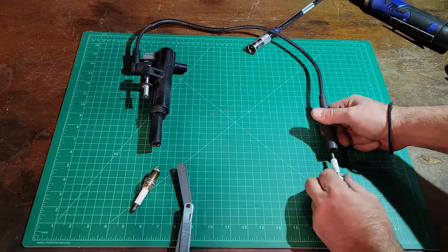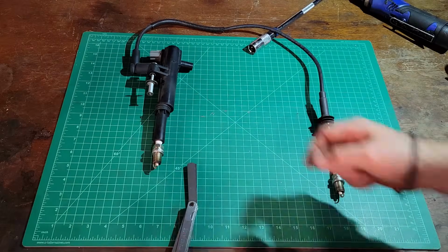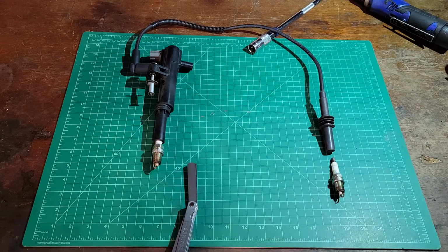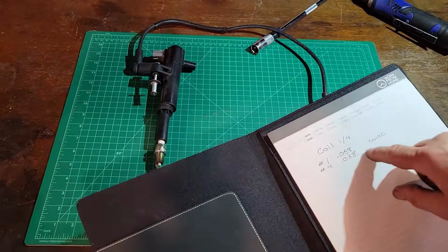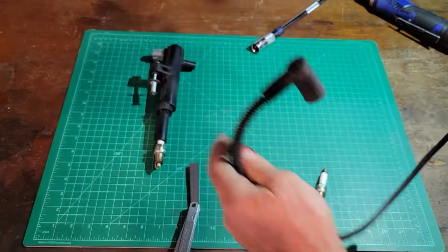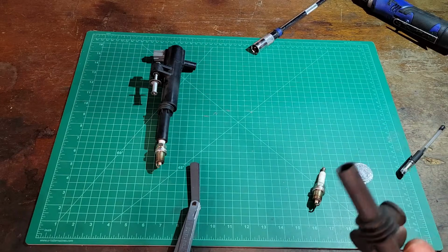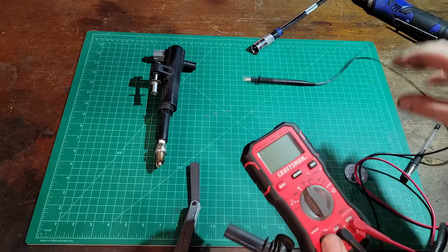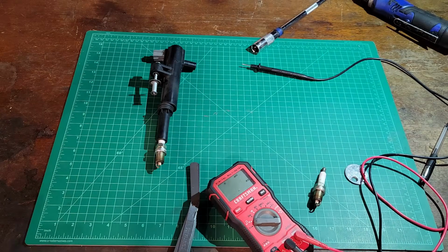I'm going to simply plug this back in when I'm done, or just put one back in the coil. And I'm writing down in a notepad the gaps, and then I'm going to measure each wire for resistance. It's pretty easy, pretty straightforward. And if you Google it, you're going to get a spec. It's like from 1K to 12K. So you're definitely going to want to look up your spec.